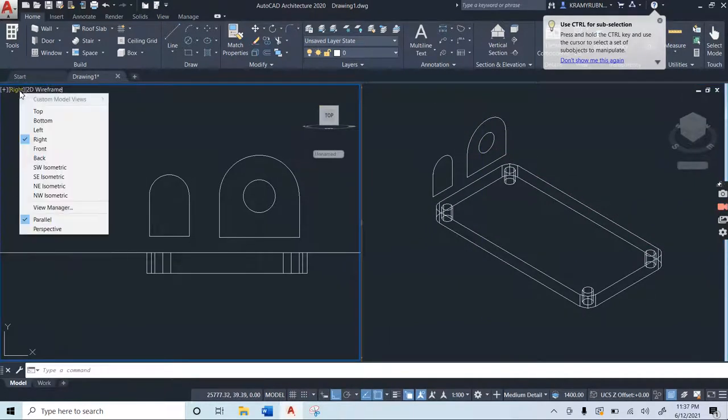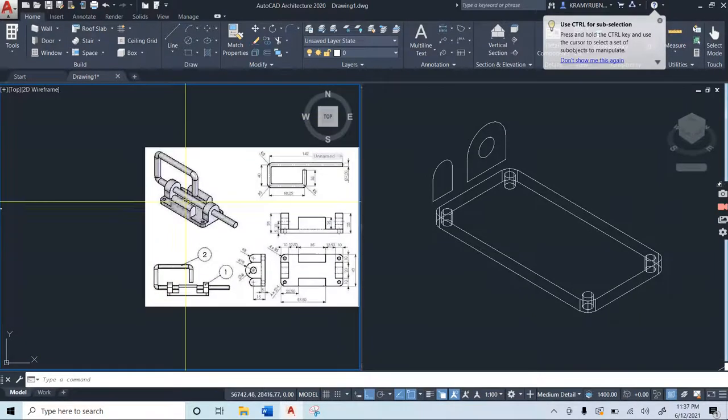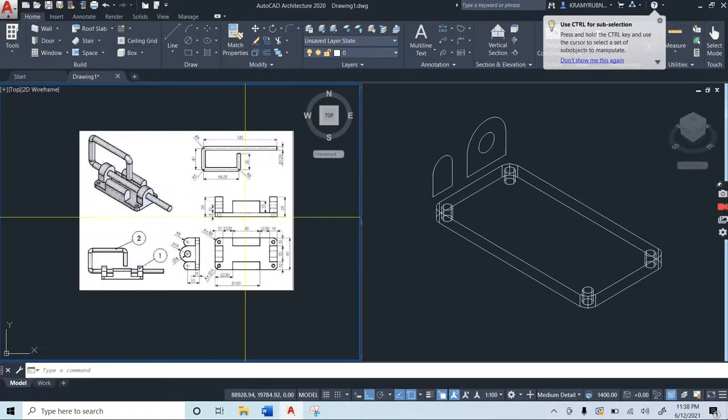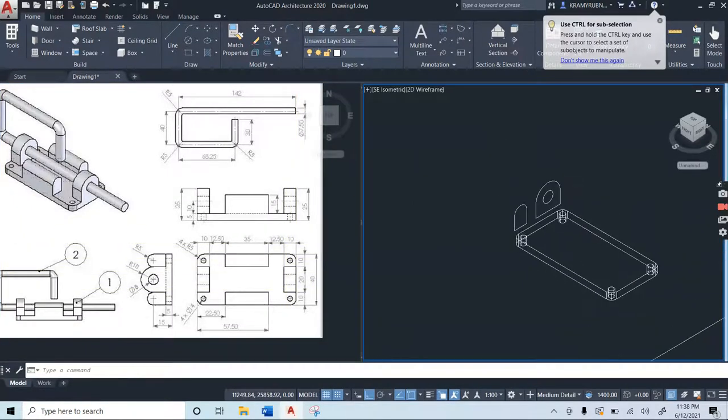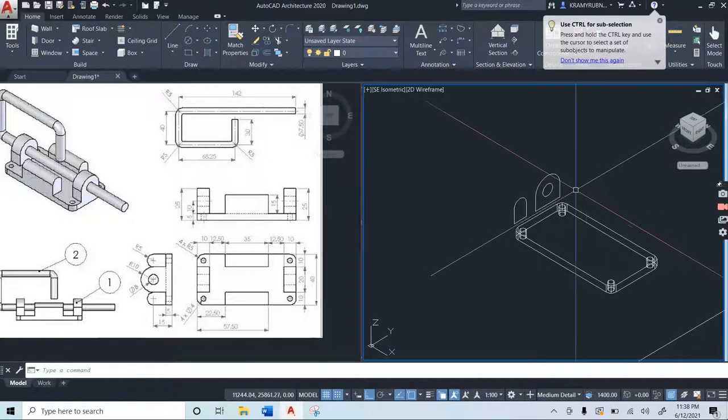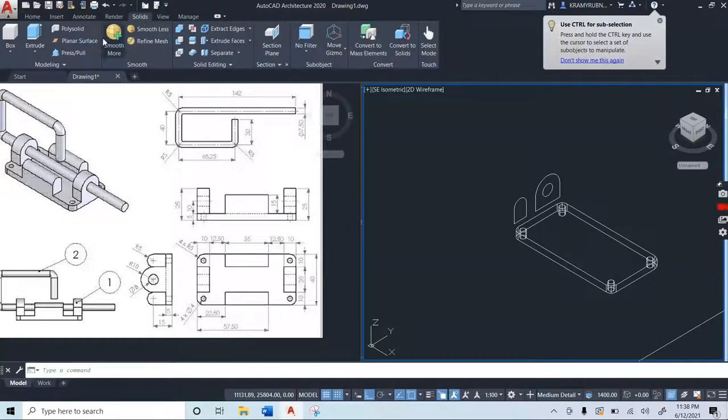Let me switch over here back to our top view, thereby allowing us to get dimensions. Now, the side piece has a length of 35 millimeters, while our end piece is of width or thickness 10 millimeters. Let us use extrude to create those two pieces. So we're going to go extrude from our solid tab, and let's extrude.